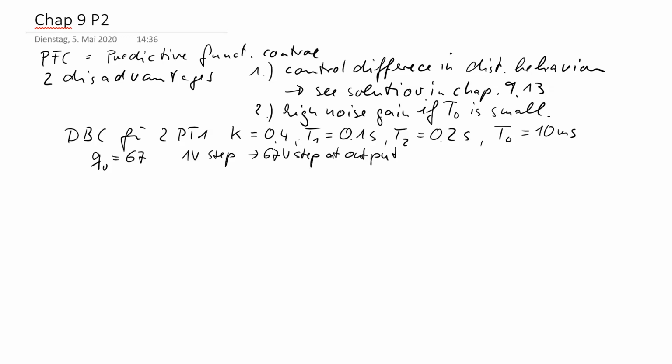That doesn't matter, but the question is what happens if I now decrease the sampling time. My version has the same gain, because without limitation it is as fast as the deadbeat controller. So the Q0 of a deadbeat controller is a very good measuring instrument to check the gain of my version of the deadbeat controller.